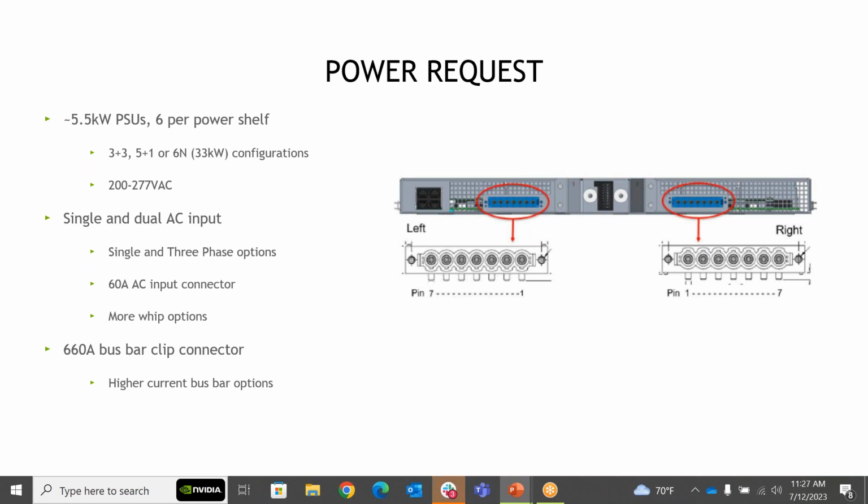Right. The solution I'm referring to doesn't rely on the BBU. The ATS is actually integrated into the power supply and utilizes the bulk capacitance to provide that hold up. So the power supplies themselves are dual input. It's offered by some of the power vendors out there, but it's not part of the standard. That's what I was referring to. So it wouldn't have the BBU requirement or bring in batteries and so forth.